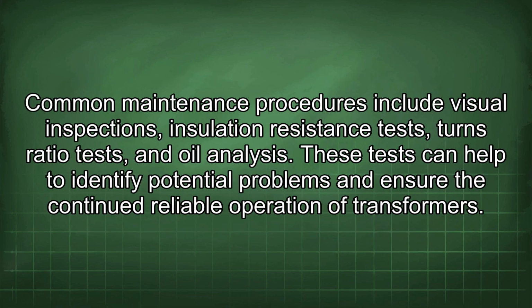Common maintenance procedures include visual inspections, insulation resistance tests, turns ratio tests, and oil analysis. These tests can help to identify potential problems and ensure the continued reliable operation of transformers.